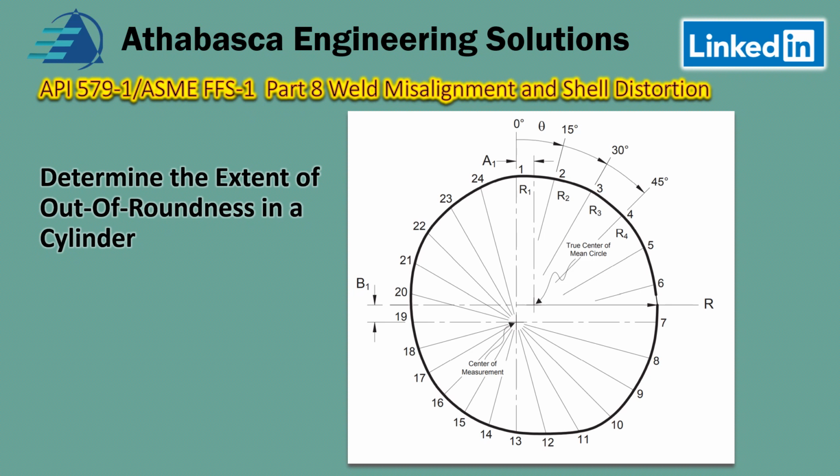So this can be quite complex, these steps. So in this case, this would be our B1, and that's our vertical distance. And so we take a number of points around this to characterize this. And eventually we want to build a model where we find the measured center of the part, and then we compare that against the true center of the ideal cylinder.